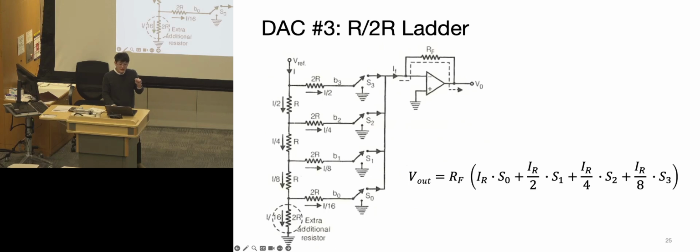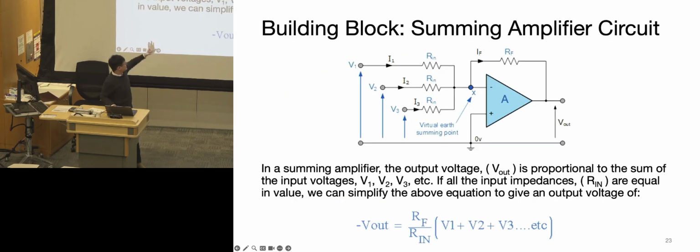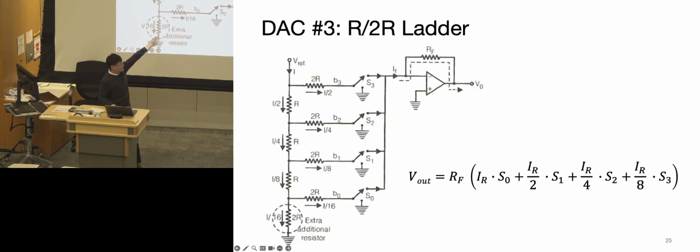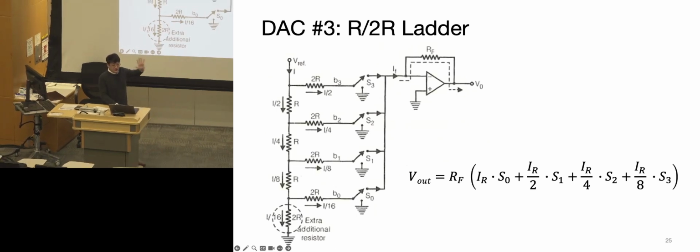how do I say this, a more standardized version of this. So instead of using an arbitrary number of Rs here, we just set it to be R and 2R, which makes manufacturing a lot easier and also makes the cost significantly less, because we only use the same values. Well, two values of them. Okay. Any questions on this or the equations here on how this is achieved?